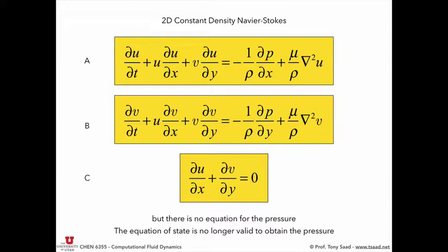But if we don't know how to get the pressure, the vorticity stream function is an approach to get rid of the pressure. Now, in vector form, when you combine these two equations together, dp dx, dp dy becomes grad p. So what is a mathematical property that can destroy a gradient?